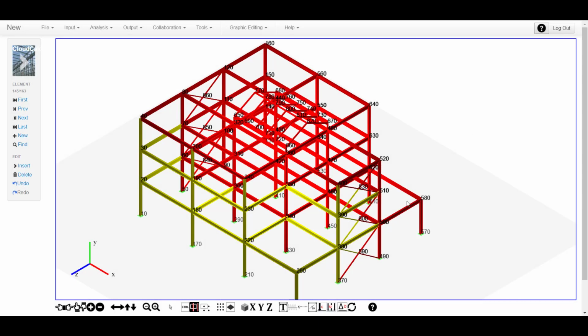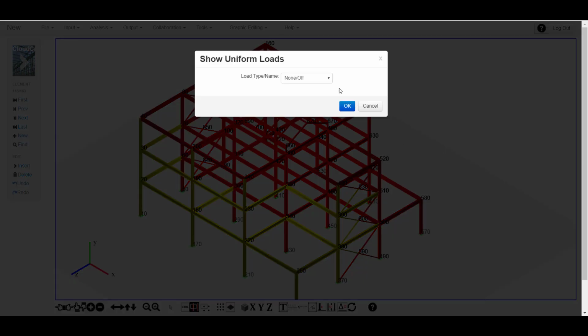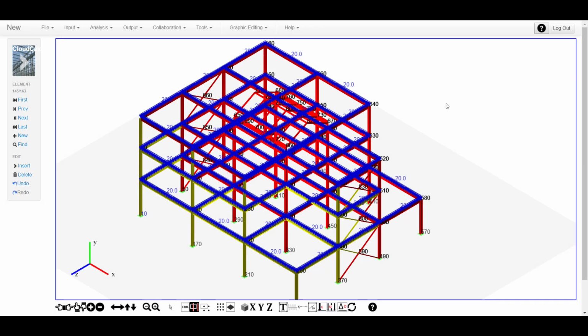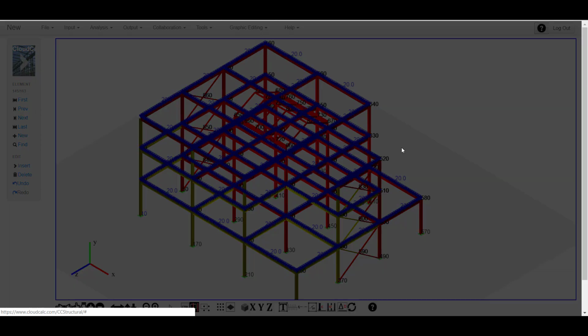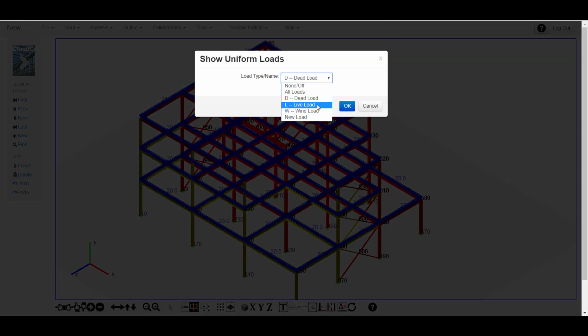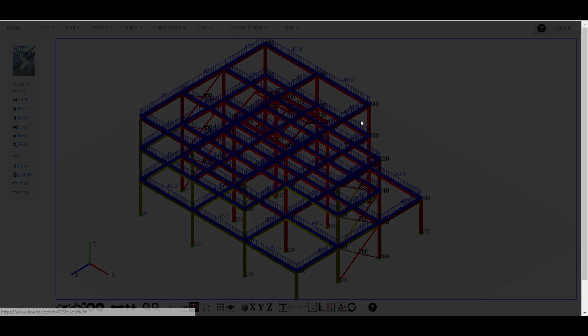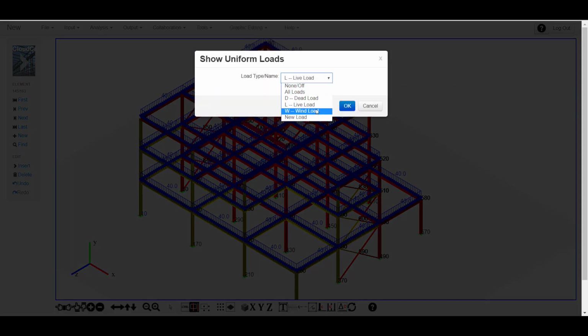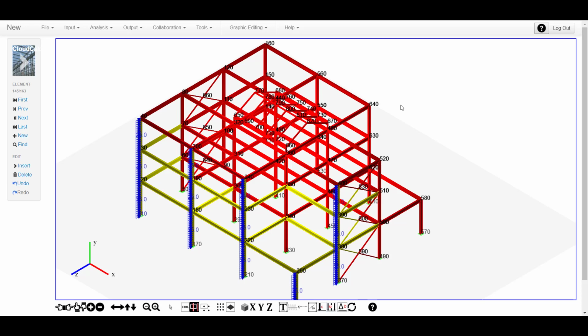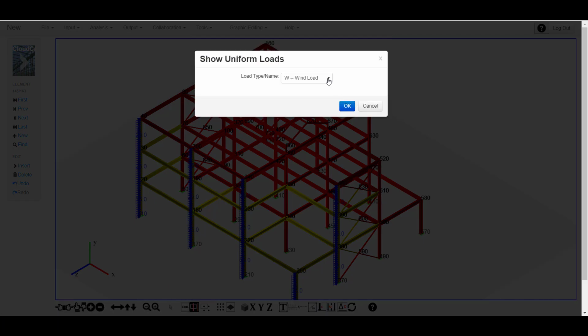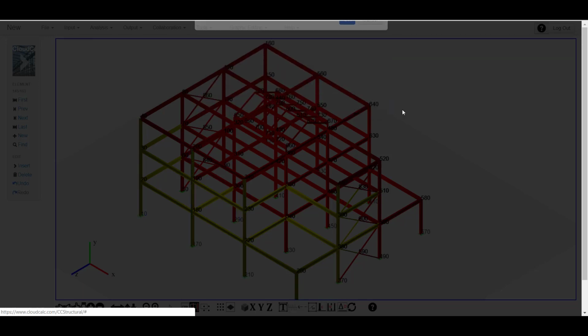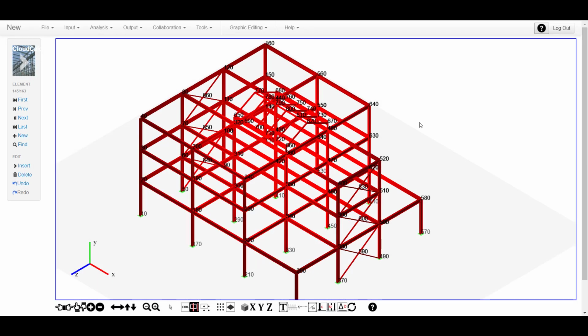and save. So now let's take a look at these loads graphically to make sure that we have applied them correctly. The dead load, we have the magnitude, it's only on the beams, that looks good. The live load shows a magnitude of 40, also applied to the beams, correct. And finally the wind load, only against those columns on that one side of the building, that's correct. Everything looks okay. So now it's time to set up our load cases.